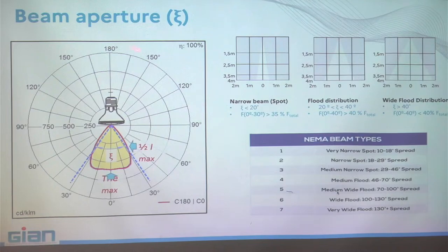without problem, and you see here, following the beam angle, we can classify the luminaires as narrow beam fixtures or wide distribution fixtures. There are some variations in the definitions in Europe. This is the European definition, and this is the American definition. We use the same name, but not exactly the same flux parts.